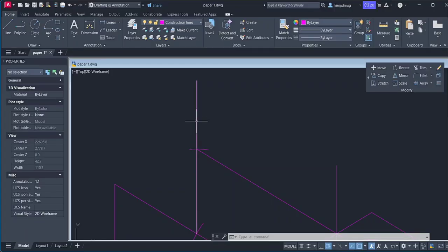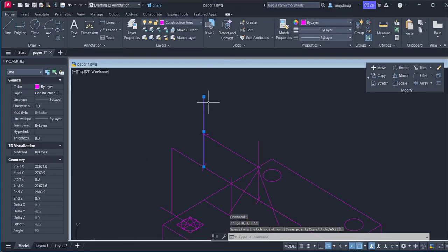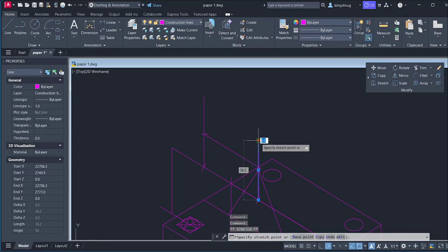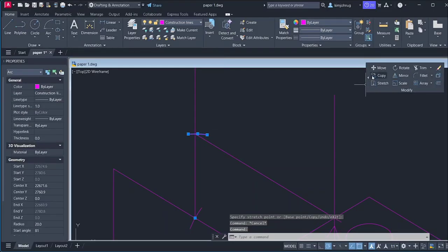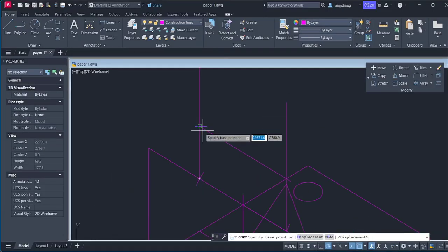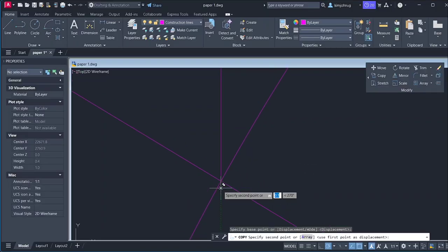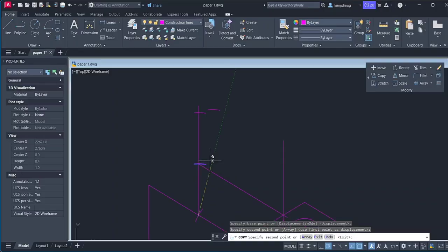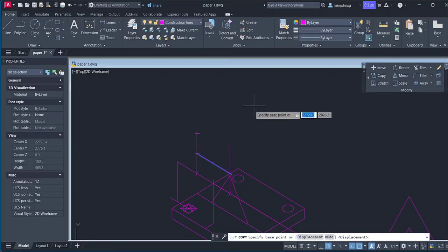Okay. So to draw that, remember the thing with doing the isometric circles using the other method, the isometric square. Whenever you're drawing them, you always draw with a complete square. So I pick this distance. I want to copy this arc from here. Okay. And I also want to copy this line here.